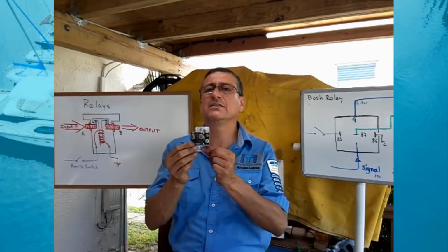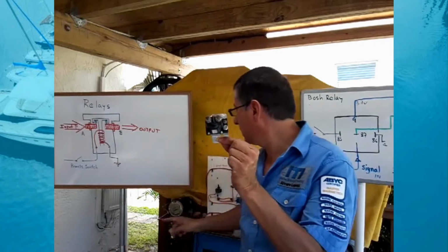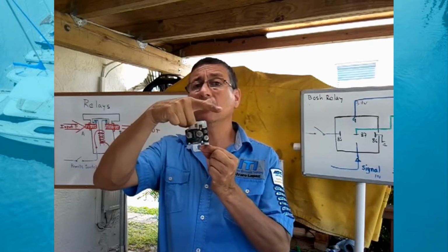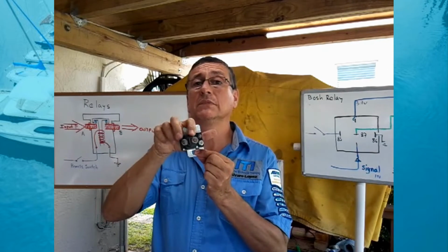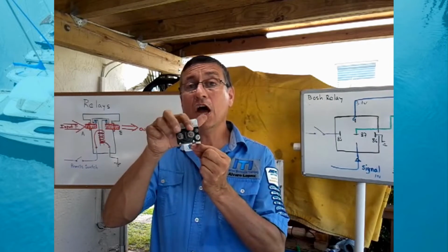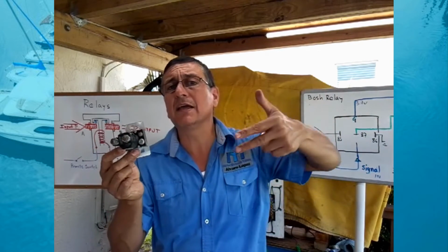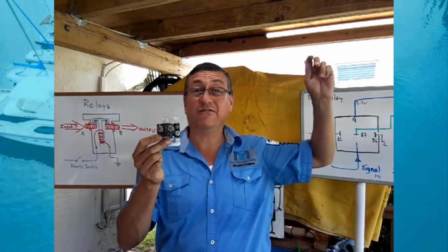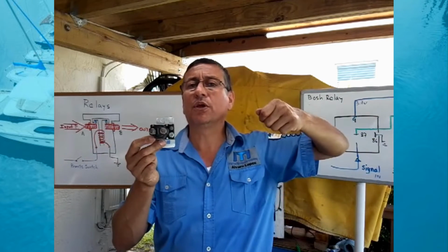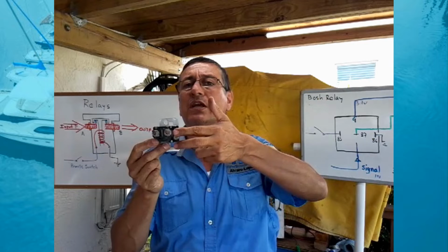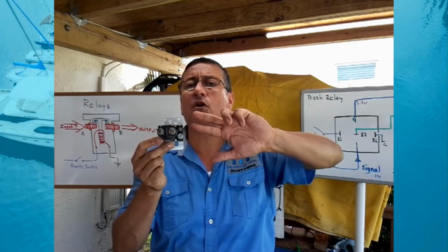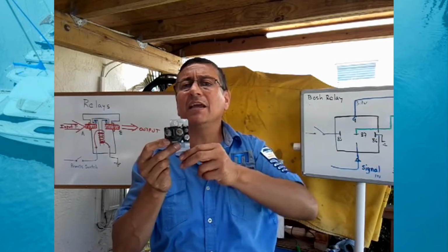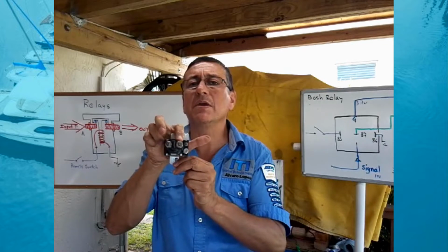And this is a relay. This is a typical crank relay. It is exactly the same as this relay, the crank relay. Position A, position B, normally open. And this closes when a remote signal enters here from another place. In your boat, for example, from the flybridge or from the pilot helm. When you activate the ignition switch, you send a small DC signal, positive and negative, or negative and positive, it doesn't matter, because this is a coil. When the signal enters, immediately the gap between A and B closes.